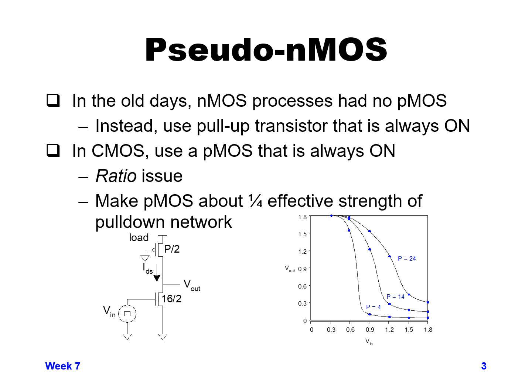What they would do if they wanted to pull things up to the VDD rail is they would use a pull-up transistor that was always on. They would use an NMOS device, connect its gate to VDD, and just have it always trying to pull up to on, and that device that was pulling up would be much smaller than whatever the pull-down stack was going to be.